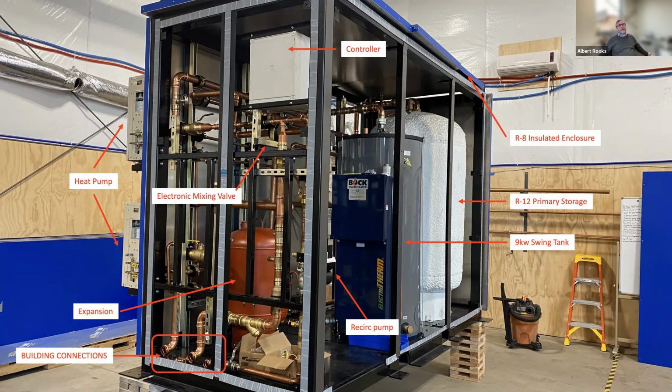In a cold climate, I don't think we have an issue on the inside, because I still think we're just going to leach a lot of heat. We certainly can put in a heater, but we don't think we need one yet. We're just making our first package delivery, so we're still learning here. What we do is heat trace the connections from the inside of that enclosure to the outside of the heat pumps, right? Because in freezing conditions, we need to insulate piping.